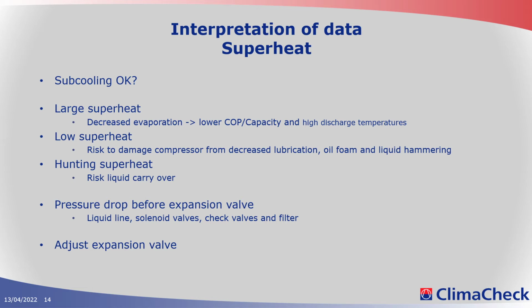Then if I have my superheat not looking correct, always before you spend time on evaluation, check that your subcooling is okay. If you don't have proper subcooling all the way to your expansion device, it's going to be very difficult to get it to work correctly.